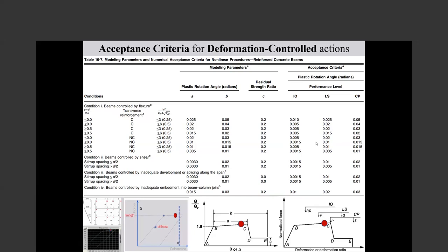Then it starts to apply a small curvature to the section, and based on the curvature and the distance of each material to the neutral line, it finds the strain in the material, then from the stress strain curve the stress, and then by the area of that section, stress to force, and then multiplying force by the distance, the moment.